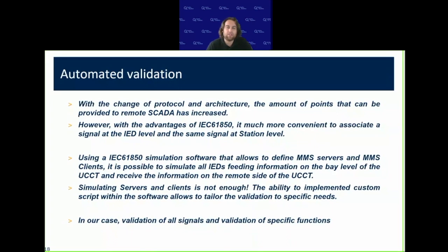Now, with the advantage of the 61850 model that we have at Hydro Quebec, it is much more convenient to validate that the signal that we have at IED level will be the same at the station level and remote level. Of course, there's the problem of device-related naming and function-related naming. However, the same way we reduced it in the configuration can be done with this validation.